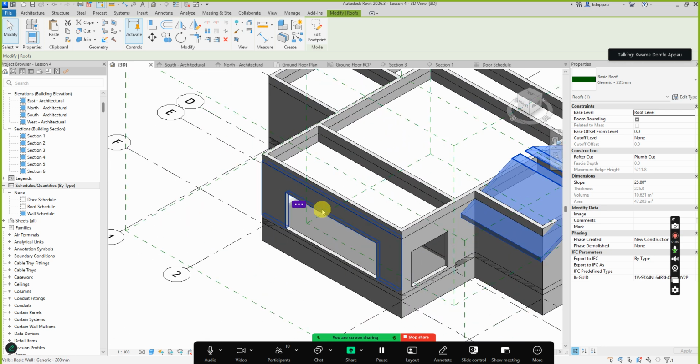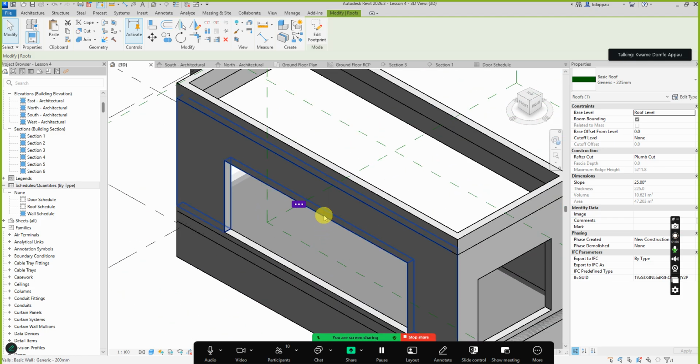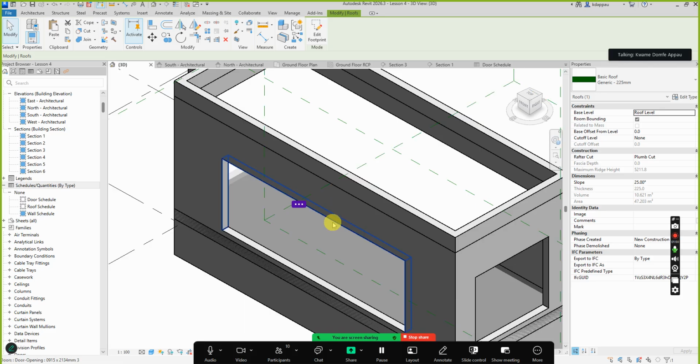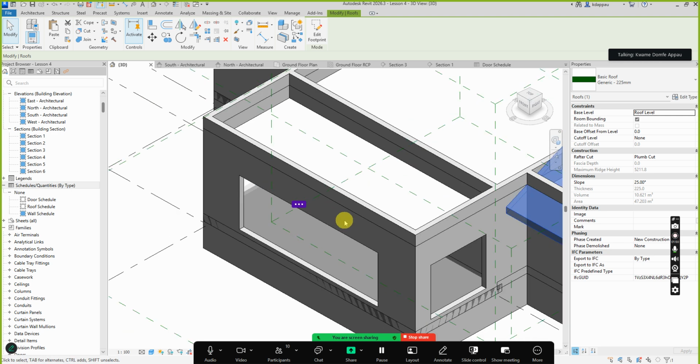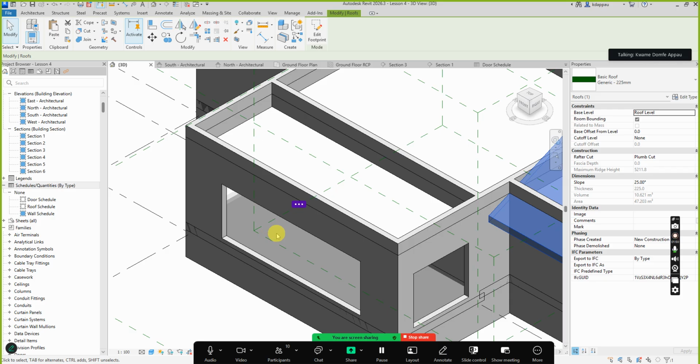So what I want to do now is a block wall that has a width of, say, 125 mm, 5 inches, and it has plastering on both sides, with plastering thickness of, say, 12.5 mm on one side and 12.5 mm on the other side. That is the kind of walls we work with. Now the plastering, whether exterior or interior, has different standards. So for now, let me just do an exterior wall with exterior plastering.